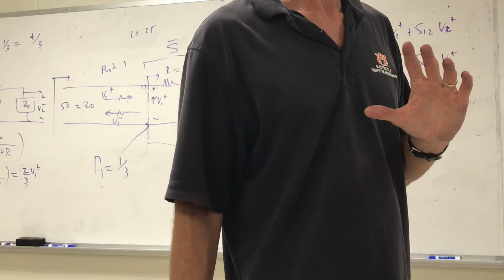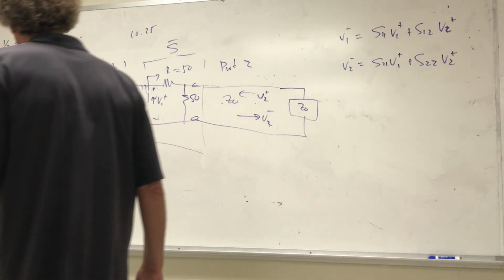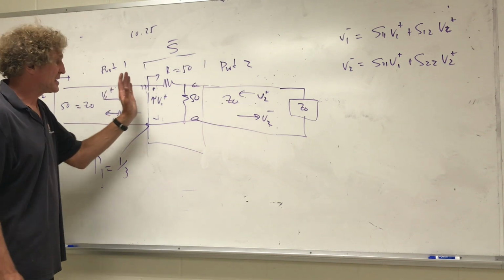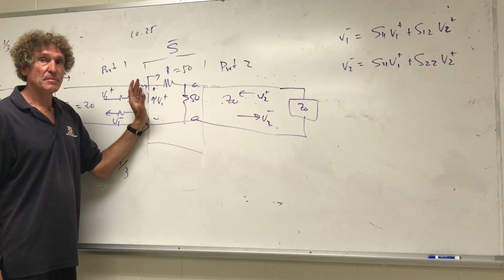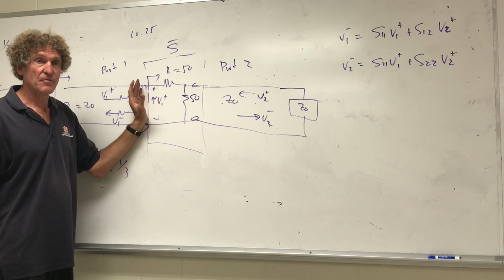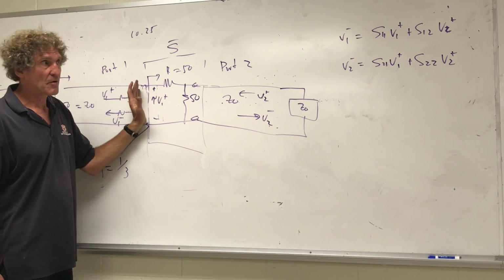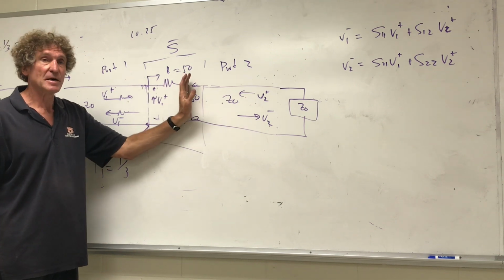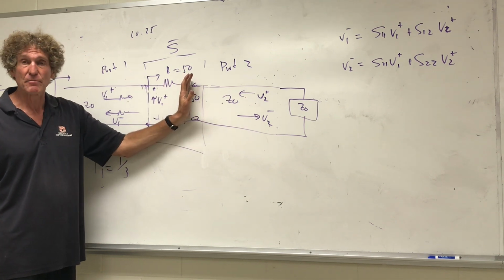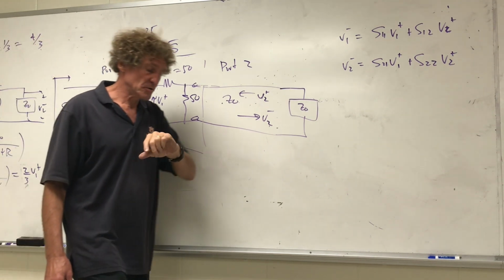And you can consider this, that everything else boils down to this. If you want S parameters, you find the input impedance on either port. They can be quite different. From that input impedance, you get the reflection coefficient. From the reflection coefficient, you basically get S11 here. You get S22 by just looking at this from the second port and doing the same thing. Then you get the transmission coefficient and do voltage division.